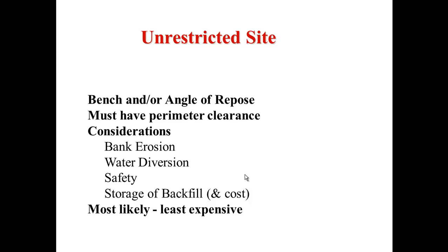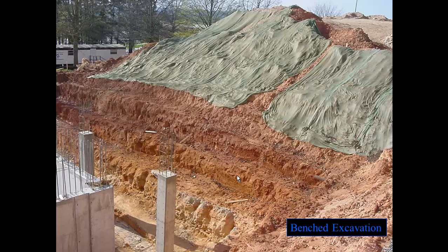And storage of that backfill, where it needs to go, when it needs to come back in, or whether it needs to be hauled from off-site. These are sometimes very expensive if you're in a site that is difficult to get material into or get it out of. Here's some benched excavation.